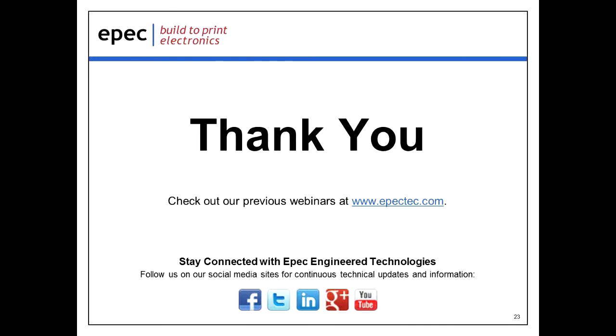The first question is, do battery packs need to be UL certified if they're going into a unit that by itself will be UL certified? It's a very good question. And the answer that we always give is yes. Because if you're going to ship that battery pack as an aftermarket product or a replacement part, you're going to need the UL certification by itself. And while, yes, it's going to go inside of your own device, it's best to have the battery pack UL certified as well, because you're going to have to ship it. You're not going to be there while somebody is putting it into the device. So it's best to have the UL protection on there, and it's best for your company for protection.